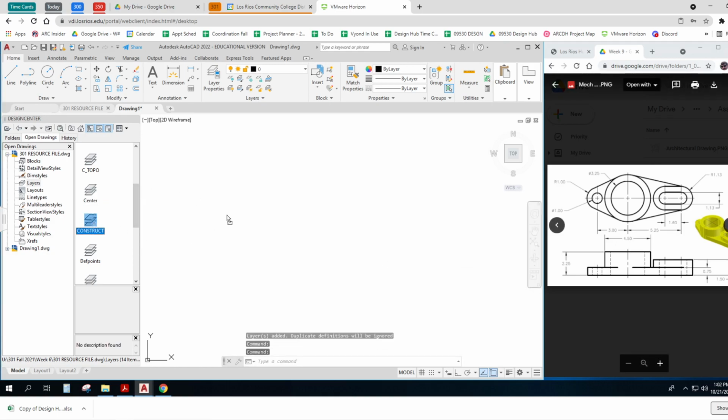I always like to have construction lines and depth points. I always like dimensions. And since this is mechanical, the object goes on the geometry layer. I see some hidden lines, so I'll do a hidden layer. I don't see any text right now, but it's odd not to have text in there somewhere too. So that's a good start.